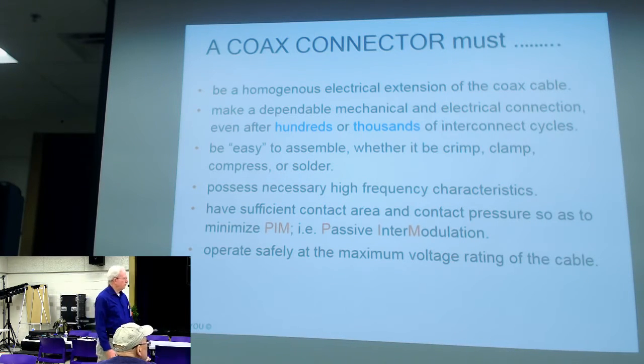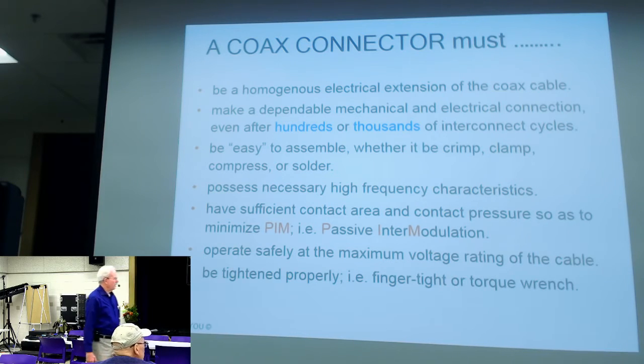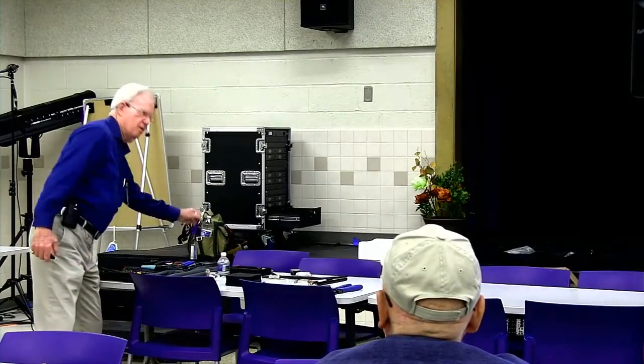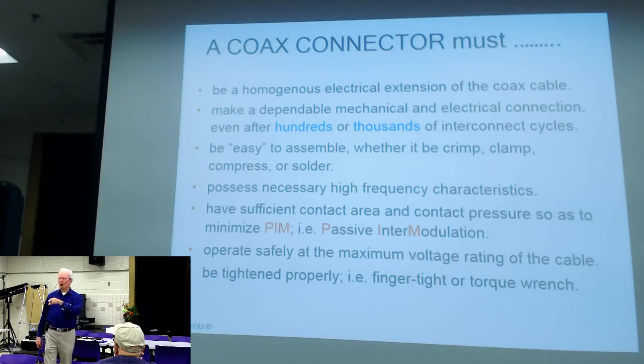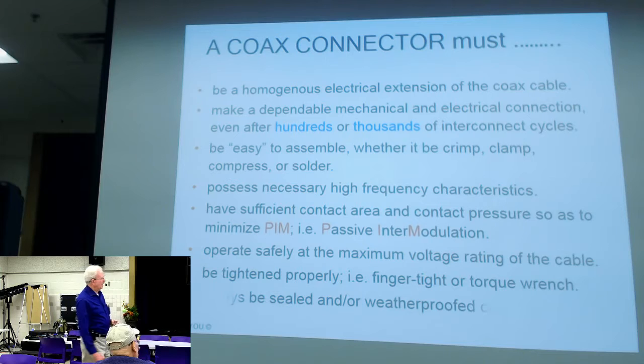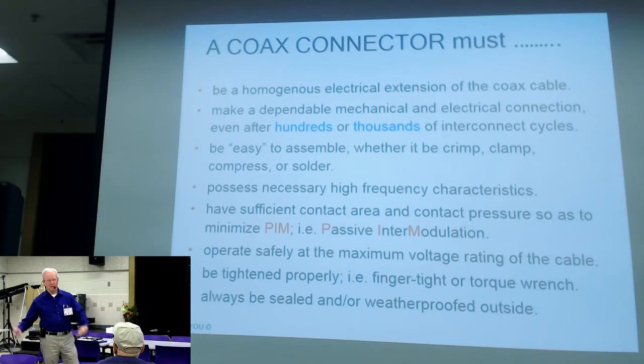Okay, got to have good voltage rating on the connector. Finger tight or torque wrench. You SMA guys, we use torque wrenches, 8 inch-pounds. And we'll talk about SMAs in a minute. And guys, if you're going to put your cable outside, please seal it, and I'm going to show you how to do that today. Just one method I use.